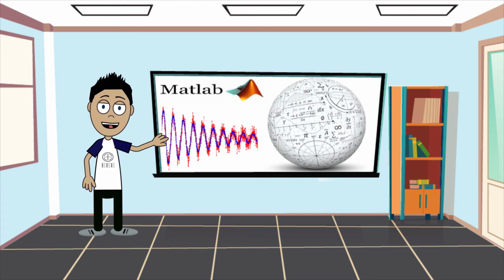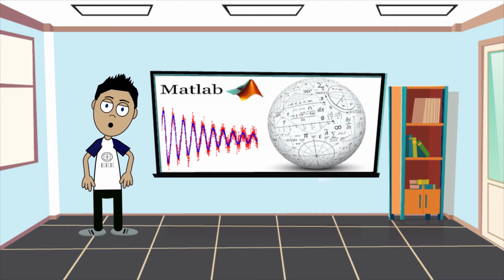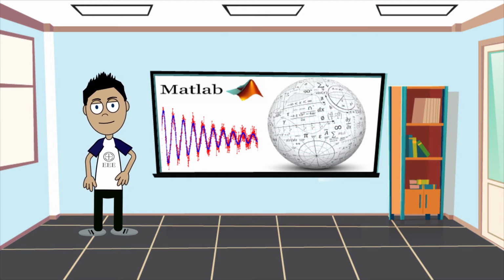In today's video we will analyse the short circuit and open circuit tests of a transformer. From the tests we can determine the equivalent circuit, voltage regulation and transformer efficiency. Both tests are explained in detail before calculating the open and short circuit values. MATLAB is then used to verify the results.